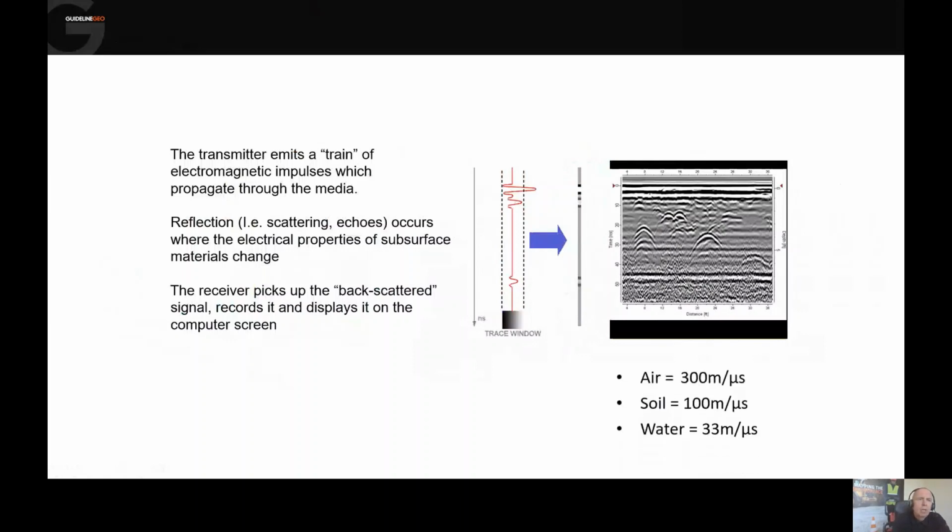Okay. We can look at the different velocities for different soils, and when we know the velocity of the different soils, we can in effect calibrate the response, and we can then convert the measurements into depth. But again, like I said earlier, that is quite typically just an estimation of the actual depth itself. But this is more for the theory side, and like I said, this is a completely different session that we can have. Yeah, that's the basics of the GPR anyway, and the EM.